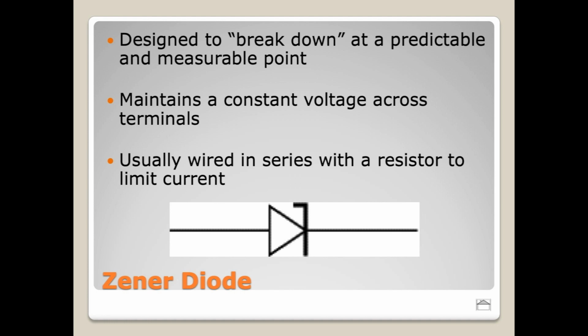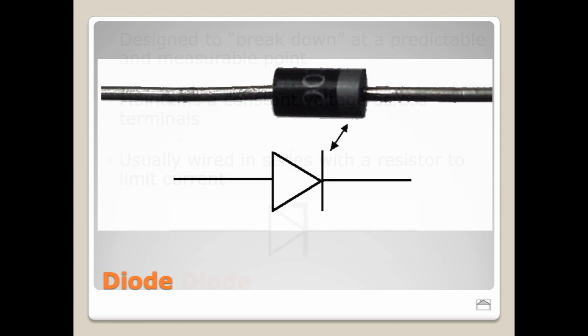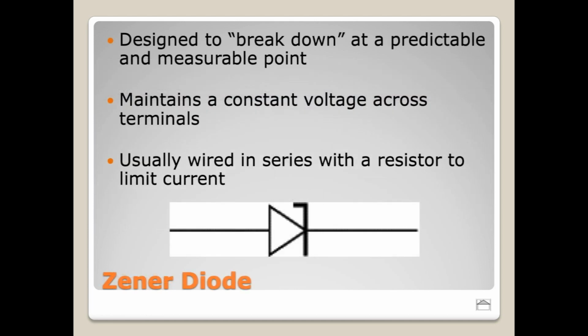Now notice the schematic symbol here. You're going to see that it's very similar to a traditional diode. You can see here's our traditional diode symbol again, and then here's our Zener diode. Notice the main difference is the flag here. You will sometimes see an additional flag down here. It looks like the letter Z, right? So that's one way that's easy to remember which one is which.